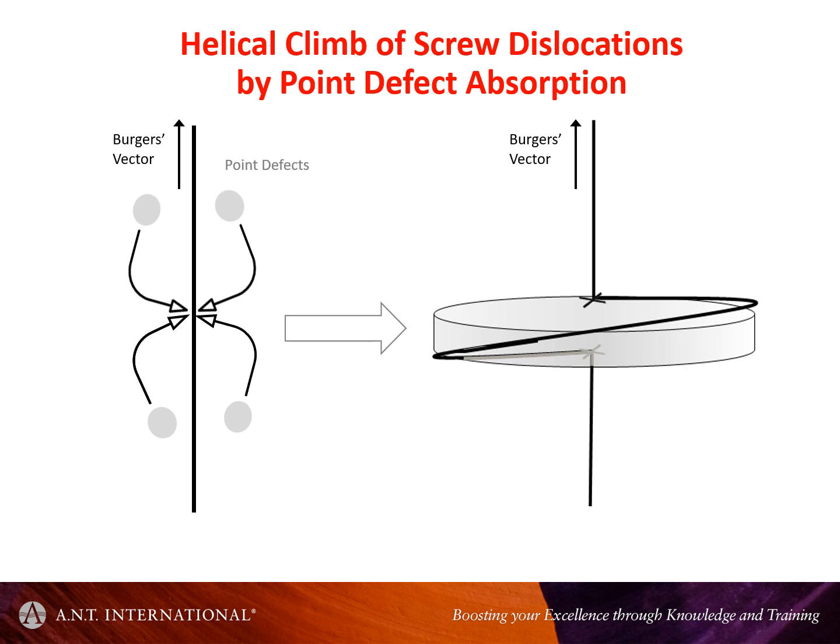But what actually happens in practice is that if you have a cold worked material, this cold worked material has dislocations in it, and if you have screw dislocations in there, you'll get these point defects which may nucleate at a certain point on the screw dislocation, rather than creating a separate loop in the middle of nowhere, which is a little bit more difficult, but having a dislocation cuts out the nucleation step,